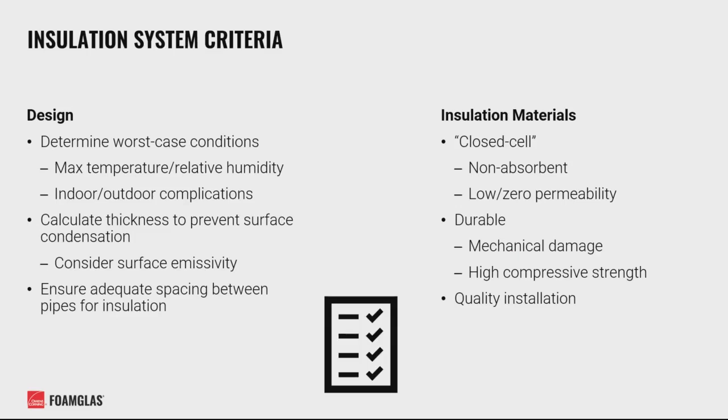It should be durable enough to tolerate its environment and have a compressive strength to withstand any weight that will come to rest against it, especially for direct burial and pipe support applications. And finally, proper installation and inspection should be carried out during construction to ensure the system is properly installed and sealed against moisture intrusion.